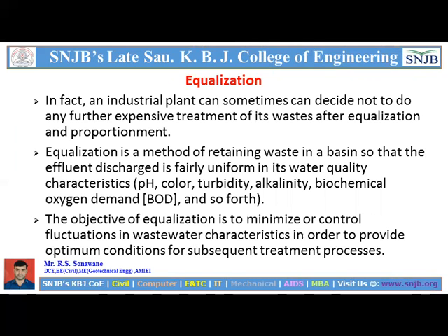The objective of equalization is to minimize or control fluctuation. So what is the first objective of equalization? To minimize or control fluctuation in wastewater characteristics in order to provide optimum conditions for the subsequent treatment process.